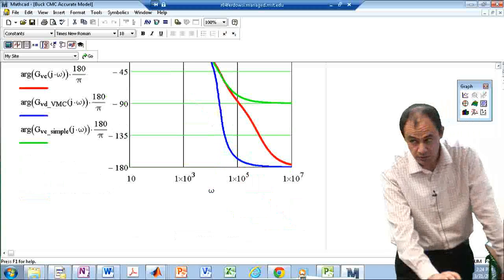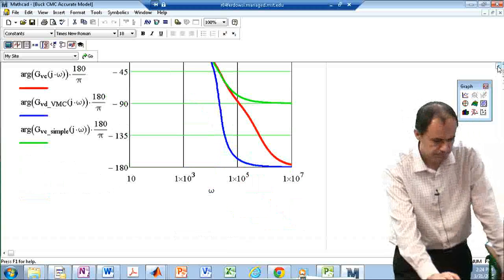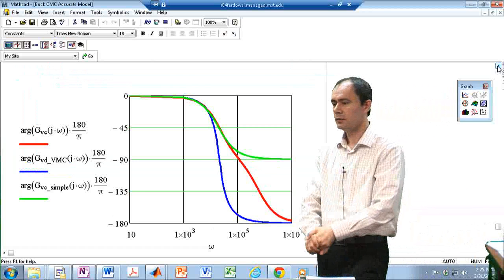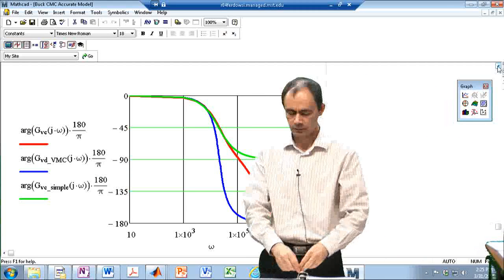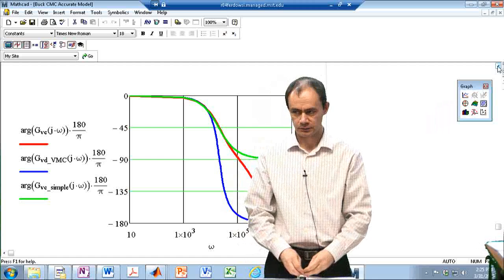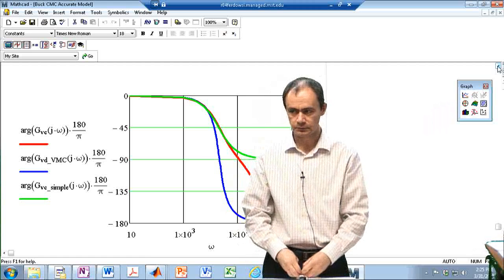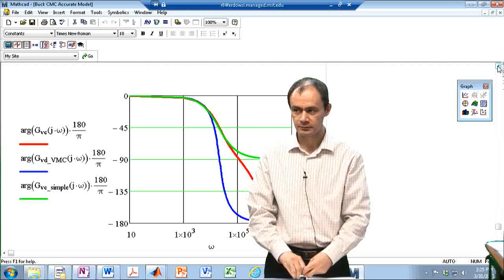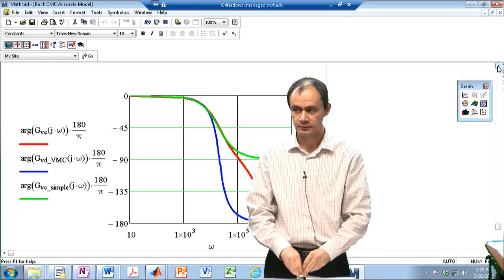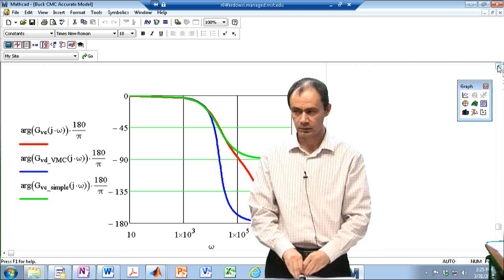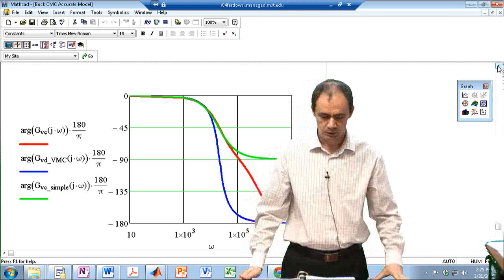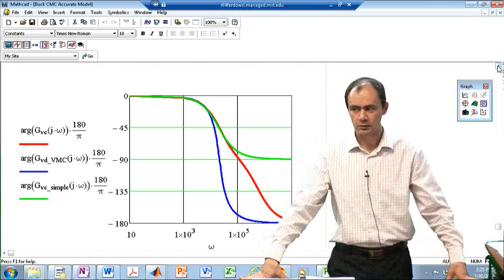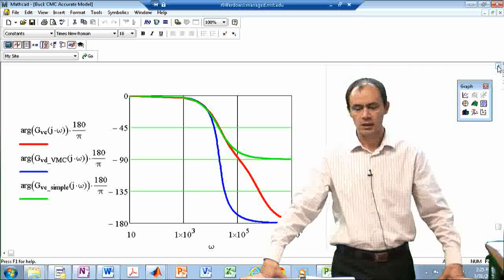Any questions so far? Yes? My question is, we usually select L and C components based on the current ripple for L and voltage ripple for C. Suppose the corner frequency happens to be, while the recommended best design for the compensator is 1/10 of the switching frequency, only around one half or 1/3 of the switching frequency. How do we go about it?